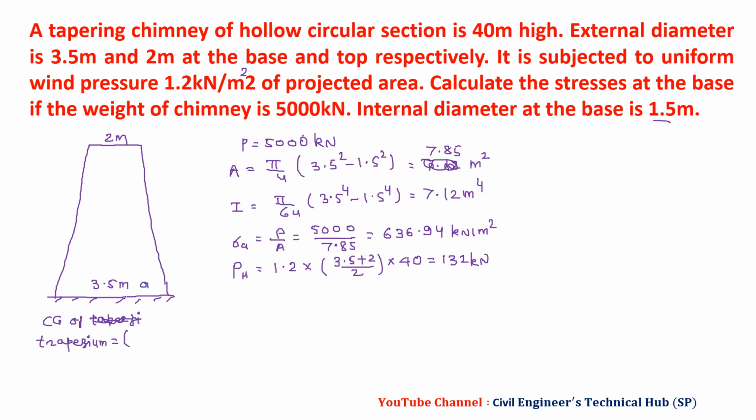If I say this as A and this as B, then we have CG as A plus 2B upon A plus B into H by 3. A we have 3.5, B we have 2, so 3.5 plus 2 times 2, divided by 3.5 plus 2, into H by 3, that is 40 by 3.